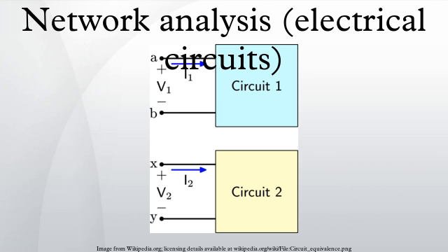In mesh analysis, the number of current variables, and hence simultaneous equations to solve, equals the number of meshes. Every current source in a mesh reduces the number of unknowns by 1. Mesh analysis can only be used with networks which can be drawn as a planar network, that is, with no crossing components. Superposition is possibly the most conceptually simple method, but rapidly leads to a large number of equations and messy impedance combinations as the network becomes larger.